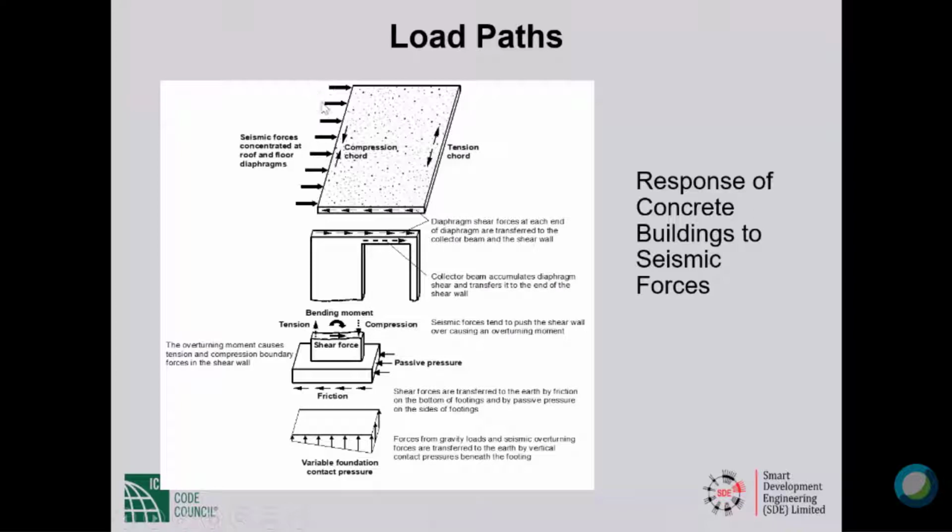Under the in-plane bending, this edge of the diaphragm develops tension. That edge of the diaphragm develops compression. The edges parallel to the earthquake or the inertia forces develop shear. Those shear forces are transferred to the supporting shear walls or frames. And those shear walls or frames, the so-called vertical elements of the seismic force resisting system, bring the forces down to the foundation, which takes them down to the ground, where all loads ultimately belong.